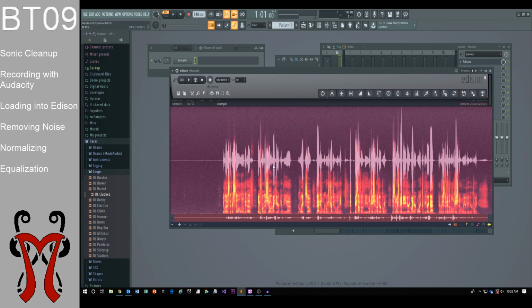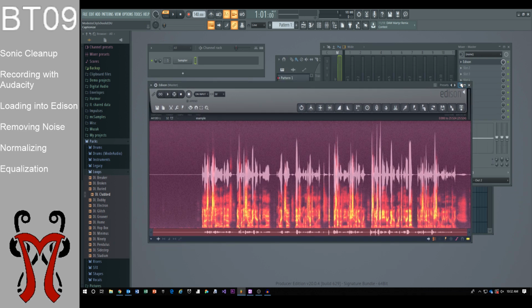Alright, the last thing that we're going to do is we're going to use EQ to try to bring out the sounds that you want. So right now, I can see that my voice is mostly down here in this range of frequency. What we're going to use is a parametric equalizer to try to bring out those frequencies and take out anything that we don't want.